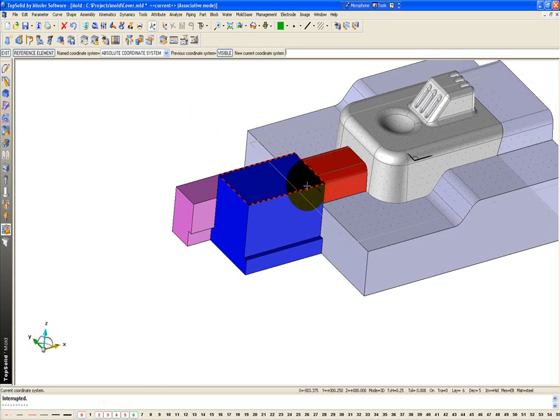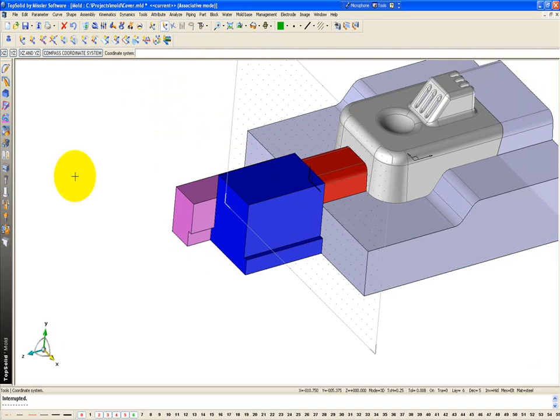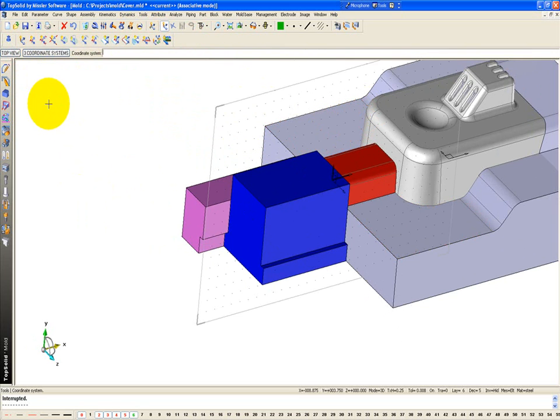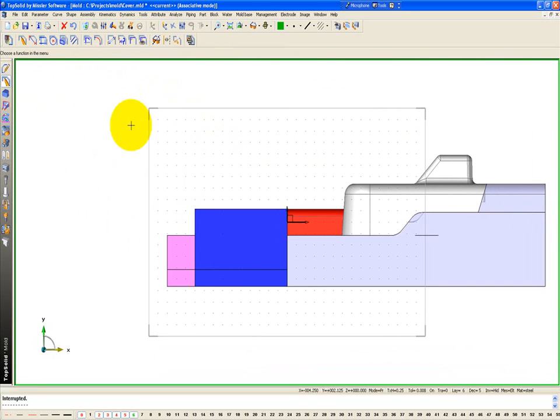Now what I'm going to do is activate this plane, as well as make a new plane off of that. So I'm going to say Tools, Coordinate System, and I want to make a plane based off my YZ of the current plane. I'm going to click on the arrow to rotate it 90 degrees, set it as current, and start a new sketch on there. In these samples you're seeing me use the Top Solid Sketcher, simply because it is the most efficient way to create some of these sketch relationships that we're looking for.